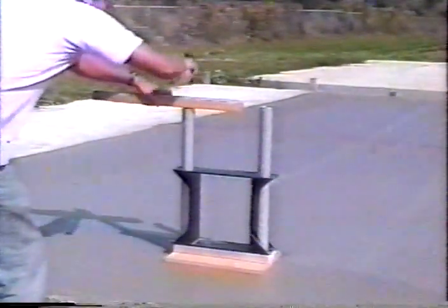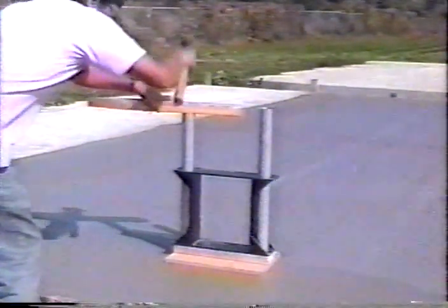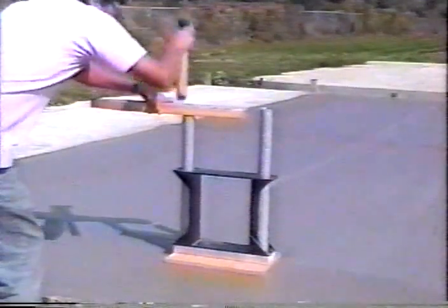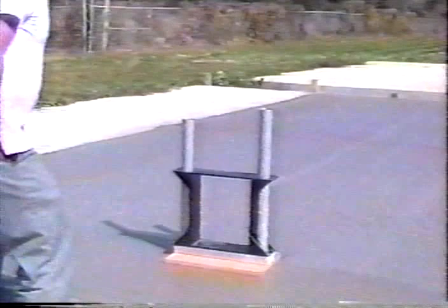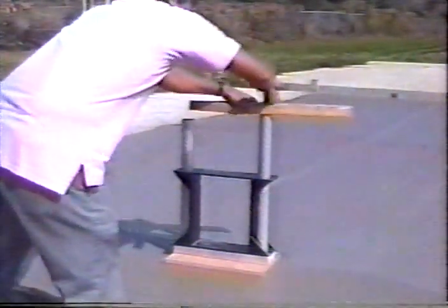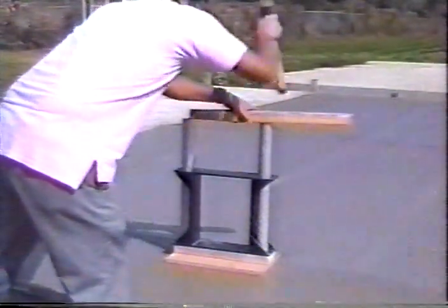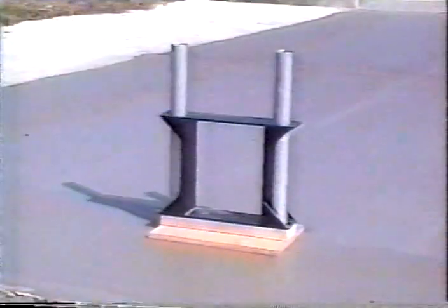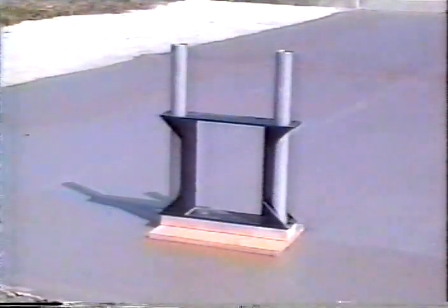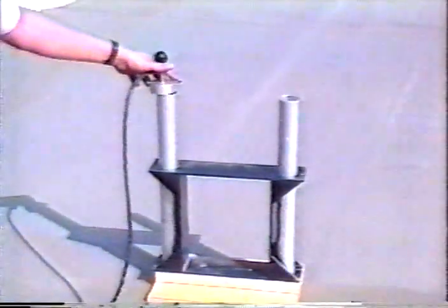In the field before testing, the nuclear count is determined on the magnesium block. Then, the steel testing frame, mounted on a base plate, is positioned on the concrete surface where a test is to be run. The frame is used to position the aluminum guide tubes that are driven into the plastic concrete to contain the two probes. The tubes are driven to equal elevations. Next, the detector probe and the source probe are lowered into the tubes.